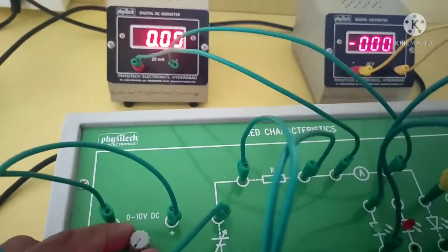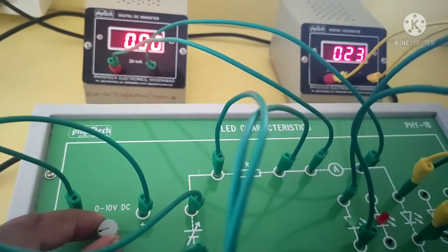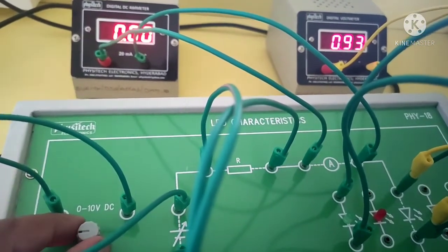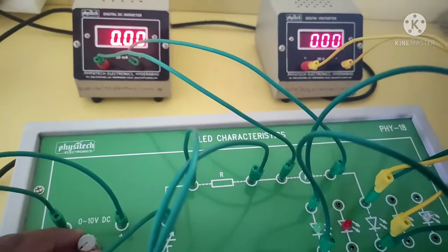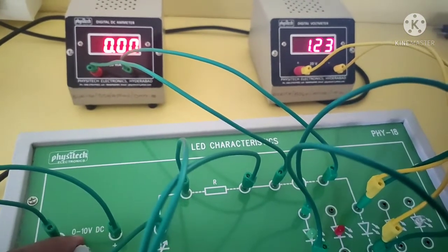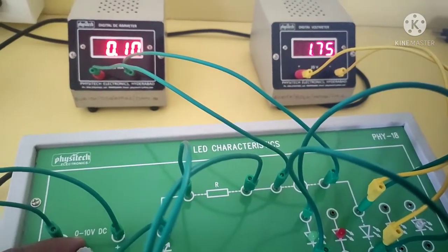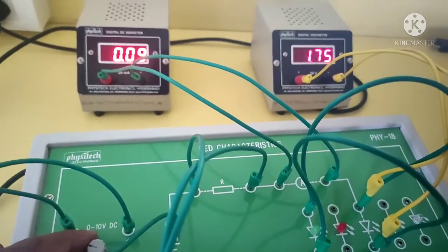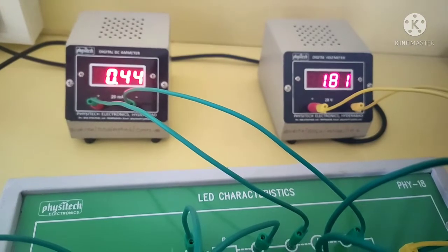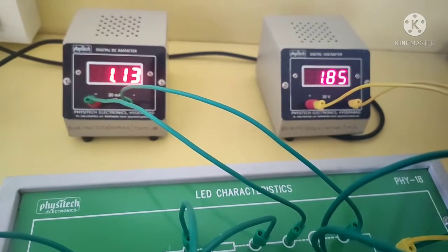So now we can vary the input voltage by using the variable DC voltage supply. We need to measure the voltage as well as the current of the LED by giving different input voltages. For example, see here we keep on varying the voltages 0.48, 0.62, 1.23, till that particular voltage the current value is 0. But when it reaches a particular voltage, the current starts to rise. We should note down all the corresponding voltage and current values for the LED. So note down all the values.